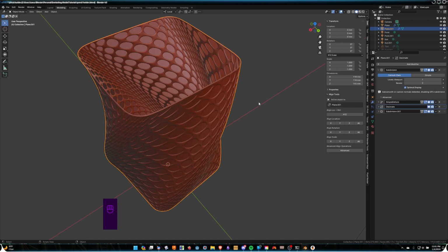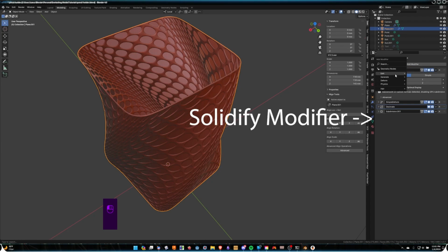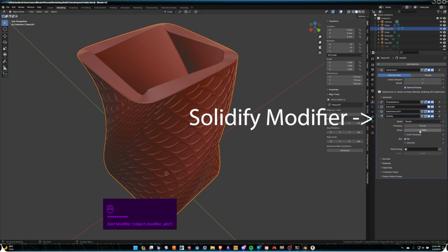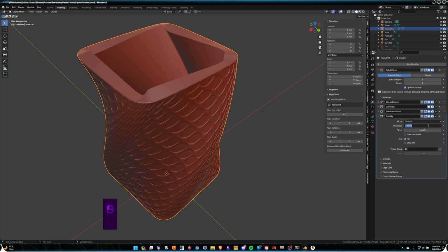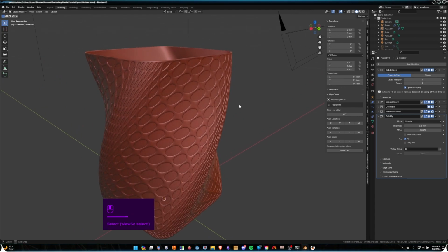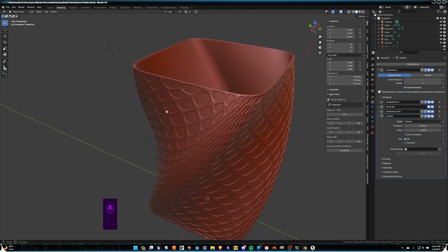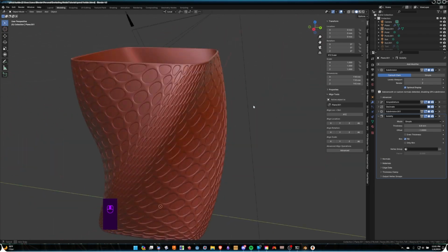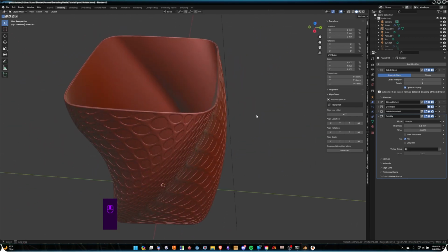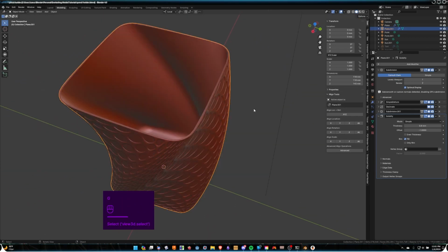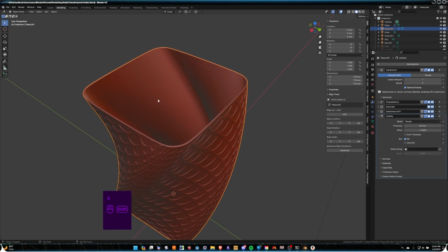So now I've already created a mesh, but the thing is I don't want this pattern on the inside and the outside. Now you can do that. You can have a pattern on the inside and the outside, and it gets rid of your bridging problem almost completely. But for me, I want to have the wireframe pattern on the outside, and I want to have it solid on the inside. So I figure out what the width of the wireframe mesh is, so it's 1.2, and I just have it basically.